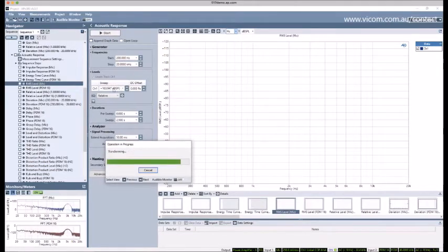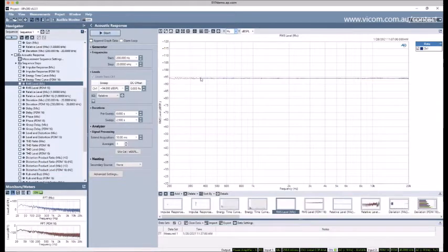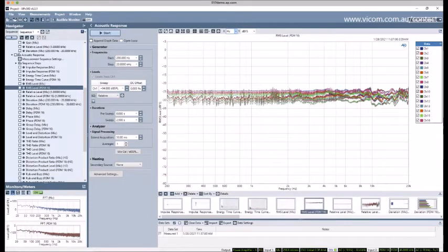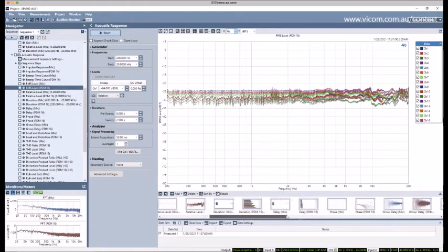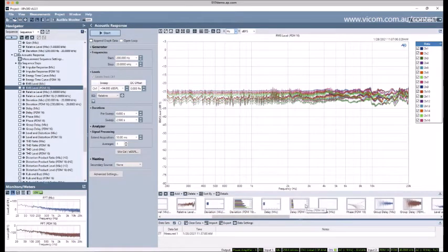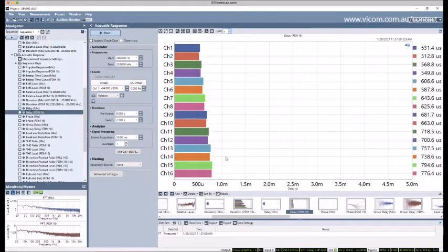It's a good thing to check the frequency response on your reference microphone for that reason, because that's a little boo-boo on my part. But now I can see that now I've applied the EQ, I get what I expect, which is a flat frequency response at my reference microphone. And now I've got the frequency response in magnitude of all 16 PDM microphones. Perhaps more interestingly, here's the delay of all 16 microphones.